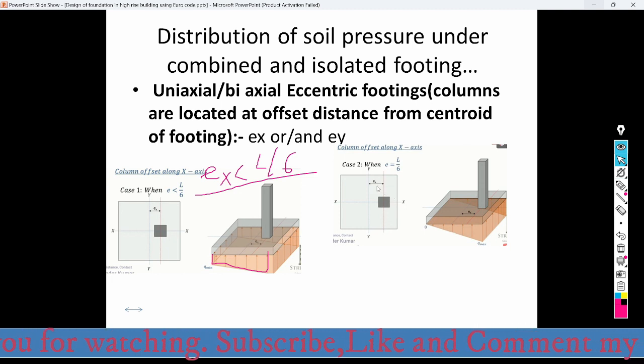And the other is when E equals L over 6, that is just here. This E is not the structural eccentricity, is not the load eccentricity, but rather it is the geometric eccentricity. So if this column is located at E equals L over 6, the distribution of the soil pressure looks like this one. So there will be zero soil pressure here and maximum soil pressure here.